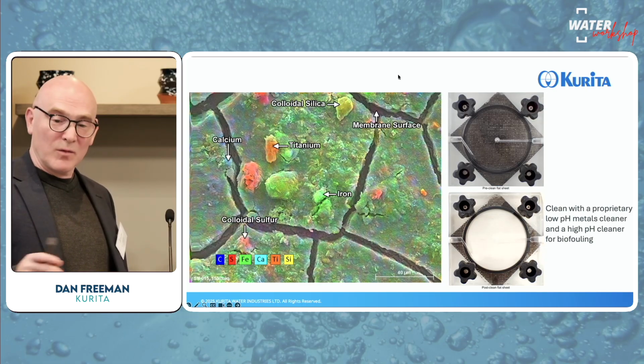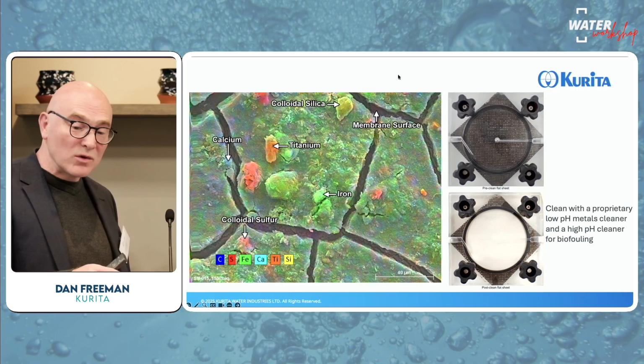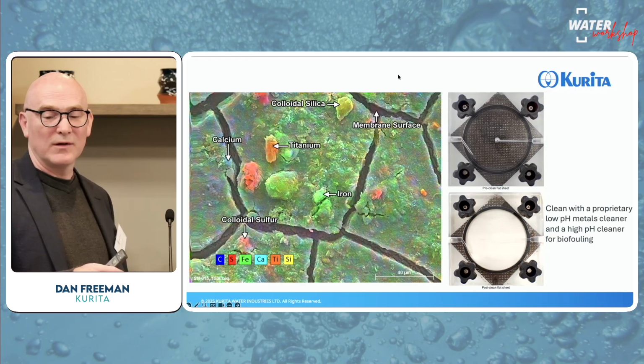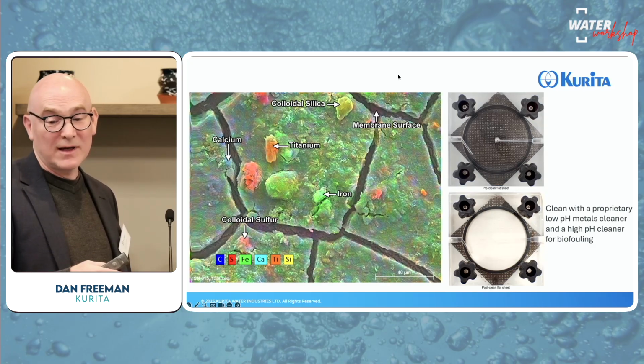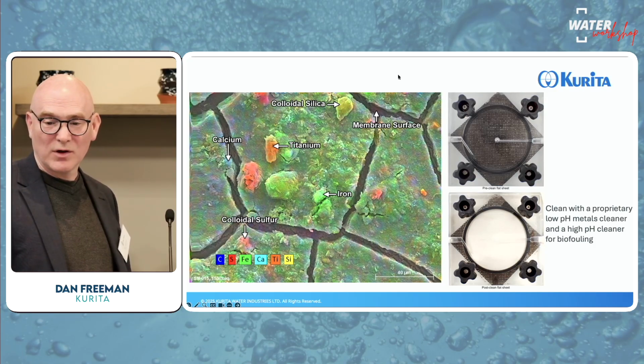This is another system from a well, actually another CEI from a well system. Again, you can see unusual contaminants here. These contaminants have come from the process upstream when they've drilled the well. So we've got titanium, which is a very unusual thing to see on most membranes, and other issues. Again, we were able to clean this particular system up with a proprietary cleaner.